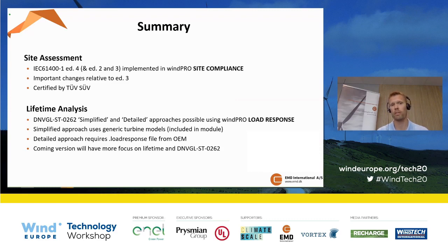If you want to do lifetime analysis, you can do the simplified and detailed approaches according to the DNV-GL standard using windPRO load response. The simplified just requires the generic models, which come with the module. For the detailed approach, you need to get a load response file from an OEM. And as you see, you can do lifetime assessments using load response, but we will make it even more visible in the coming version.